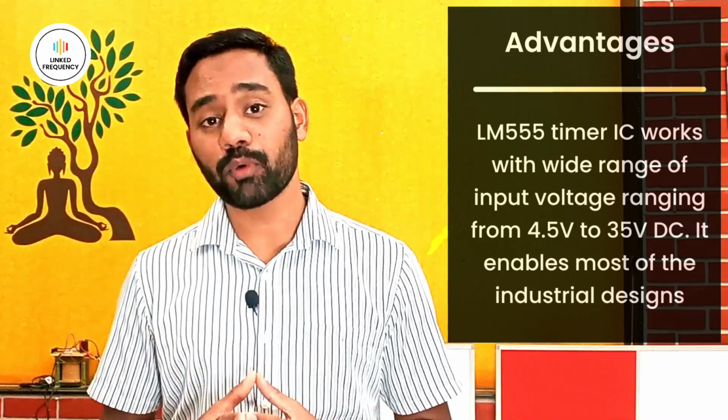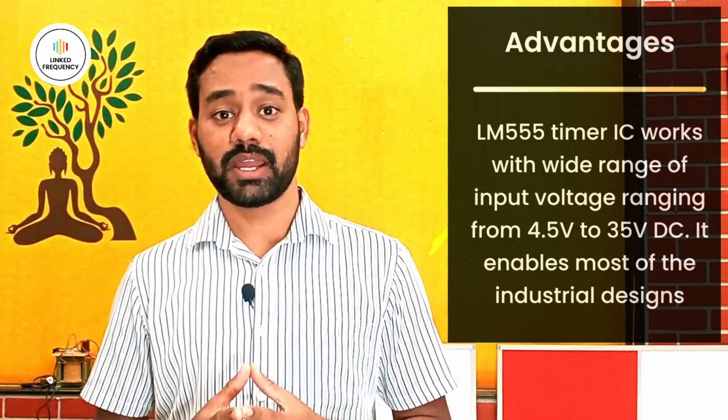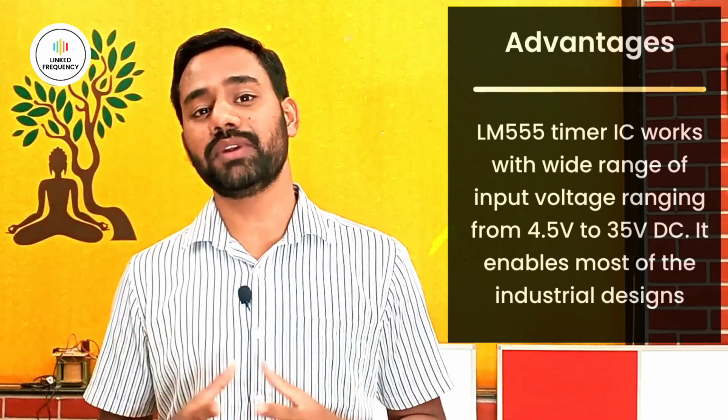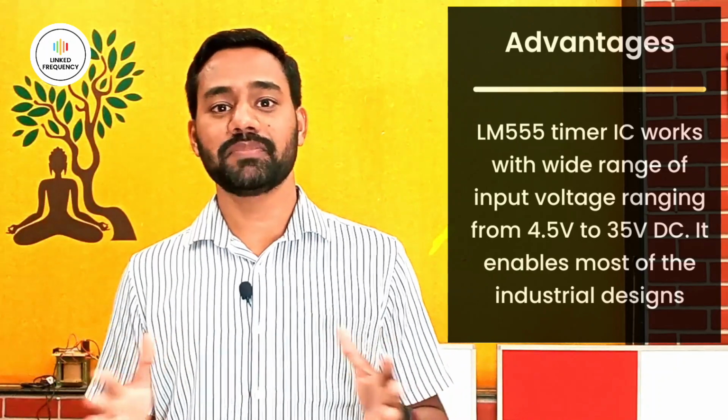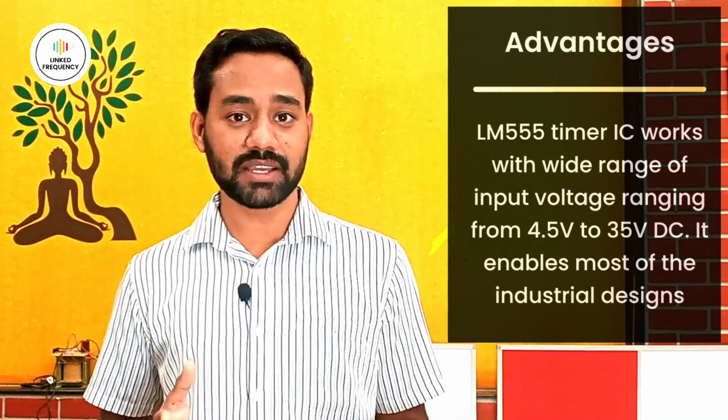Second advantage is this IC works with a wide range of input voltage. For example, 4.5 volt to 35 volt. Most embedded systems work at 5 volt, most PLCs work at 24 volt, and the automotive industry works at 12 volt. That's why the range from 4.5 volt to 24 volt is sufficient for the DIY segment as well as the industrial segment.